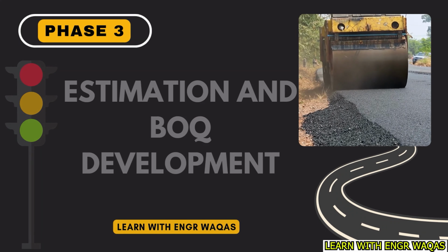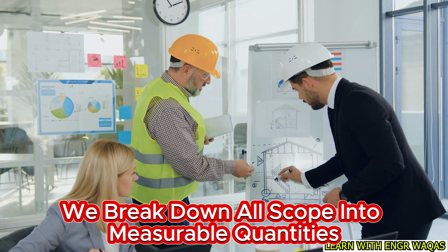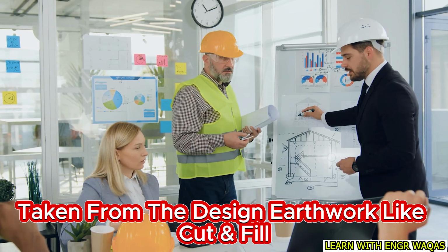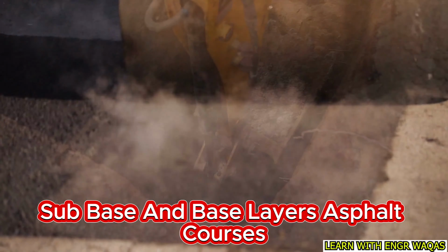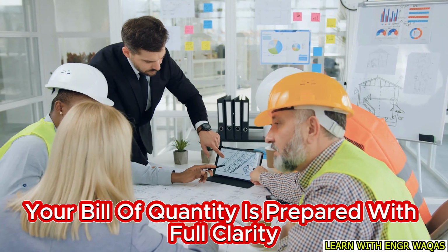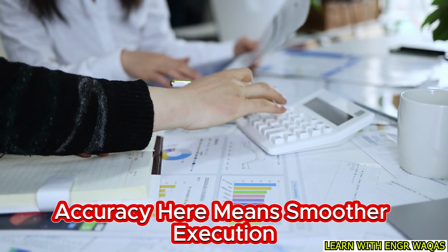Phase 3. Estimation and BOQ development. Now, estimation time. We break down all scope into measurable quantities taken from the design: earthwork like cut and fill, sub base and base layers, asphalt courses, concrete works for curbs and sidewalks, drainage, lighting and marking. This is where your BOQ, your bill of quantities, is prepared with full clarity. Accuracy here means smoother execution later.